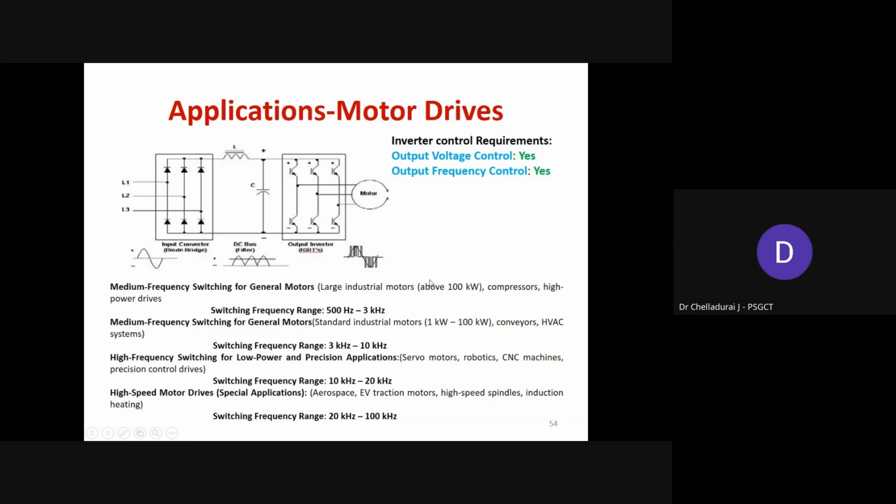One very important point is, if the load capacity or load power requirement is very high, or the VSI is connected to the grid and the amount of power injected into the grid is more, then the switching frequency should be limited.